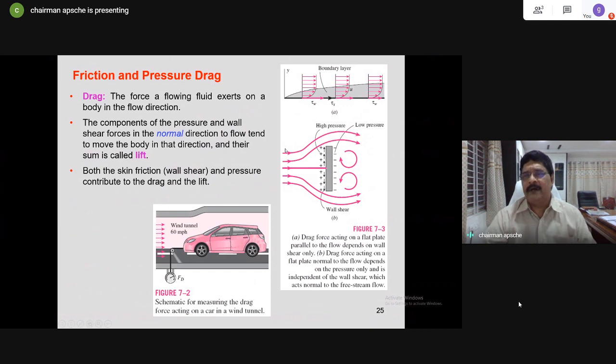That's it. What is the difference between average and local heat transfer? I told you. Now, flow over blunt bodies, I told you, flow separation and pressure drag also I said. See, when a fluid is flowing, what is the pressure at the frontal area, what is the pressure at the back area, and in some cases when flow separation is taking place, you will have negative pressures, and therefore the pressure difference also drags the vehicle, and that is called pressure drag.